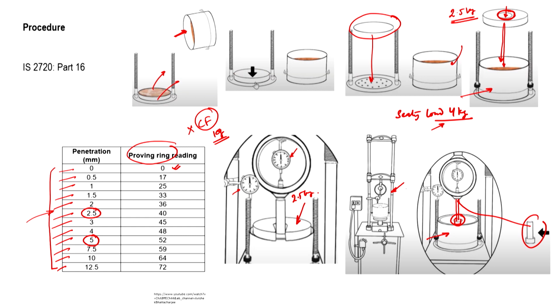So, let us say you have the calibration factor, you multiply it with all the values and you get the values in kg. And then if I want to convert this value into the pressure, I have this load, I will divide by the cross sectional area.